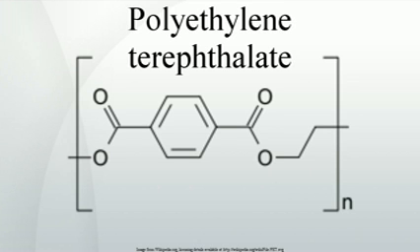Accumulation of gels and long-chain branching defects, and the number, concentration, and variety of non-polymer organic and inorganic foreign substances are increasing. With every new thermal stress, the organic foreign substances will react by decomposition. This is causing the liberation of further degradation-supporting substances and coloring substances.